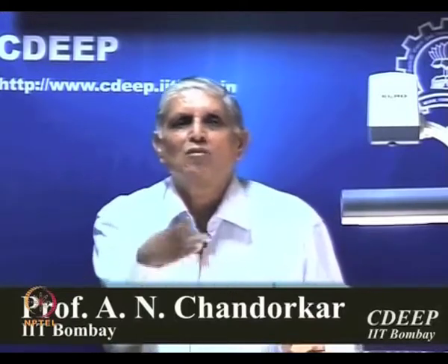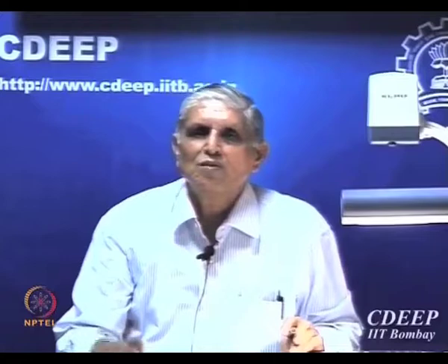Is that clear? Last time someone was asking, if small VGS changes, what will happen? That is our assumption: in the range in which I am looking at the small signal, plus or minus dx, I say x0 remains as if constant around x0, and therefore currents are only proportional to DC.